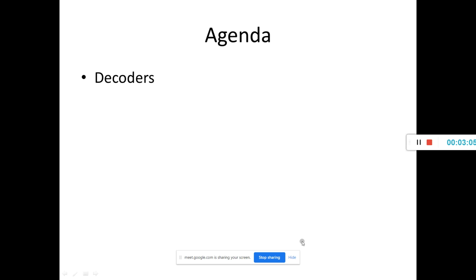Suppose we have 3 inputs at the decoder. Then 2 raised to 3, that is 8, output lines will be there. N is the number of inputs, 2 raised to n is the number of outputs. Now if at the input side I choose 0 0 0, at the output side the first output line will be selected. If I choose 0 1 0, then the third output line will be selected.